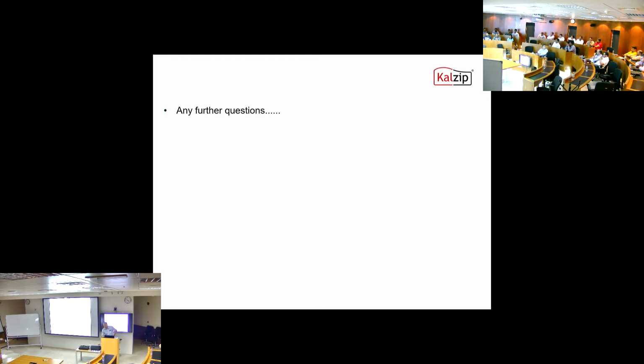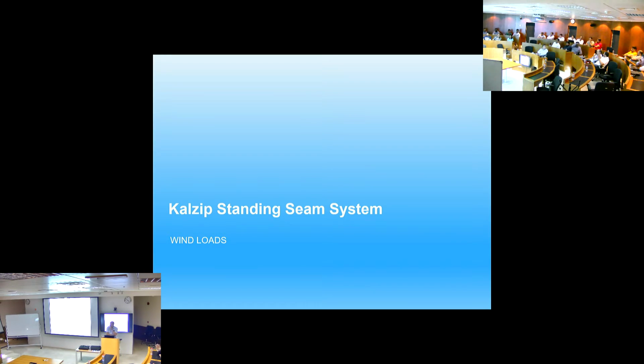Now I have seen, for example, lifting beams, where they take it all the way, with the length appropriate to the curvature, and lift it. For straight sheets, usually we go upward, downward. For the curve, you put the sheets on a pallet. You can either use a lifting beam or slings, and depending how heavy the crane is, maybe they could lift 10 sheets up onto the roof. You won't put the kit up onto the roof, because with the curved sheet, you roll form the straight sheet first, then curve it on the ground, stack it, and then lift it with a lifting beam.